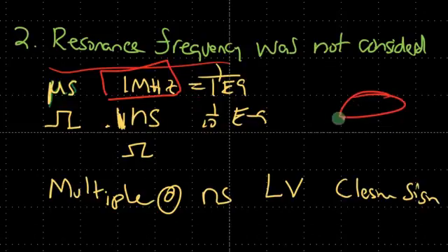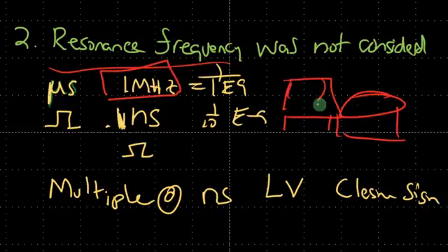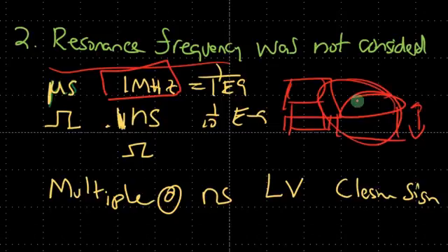And for this application, you should use a disc. Square piezos have different resonance frequency modes, so if you're using a thickness type of resonance, a disc is the best bet. Although the square can be used, there are a lot more complications. A disc is much simpler and better.